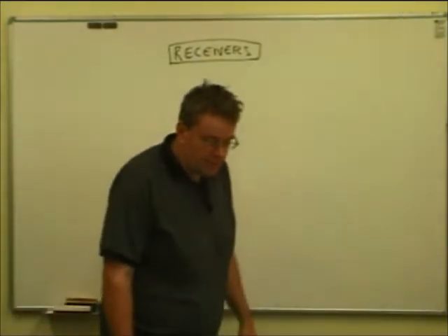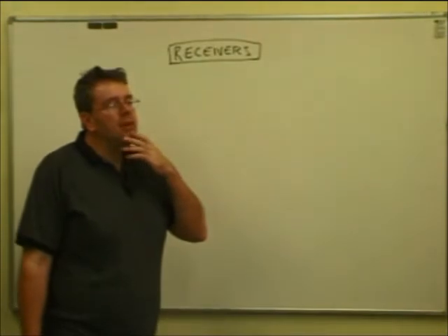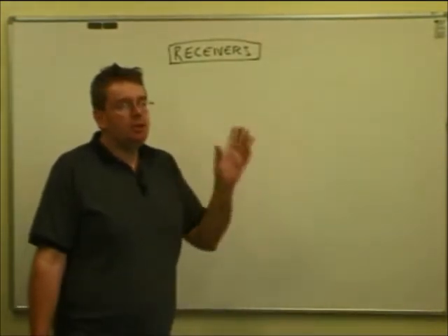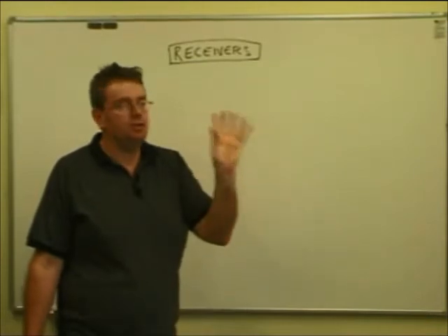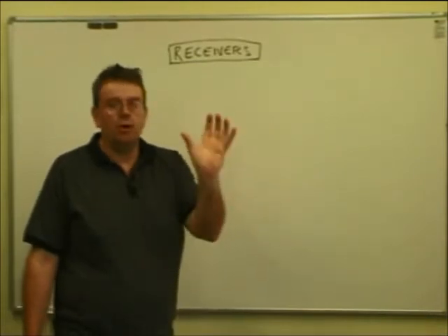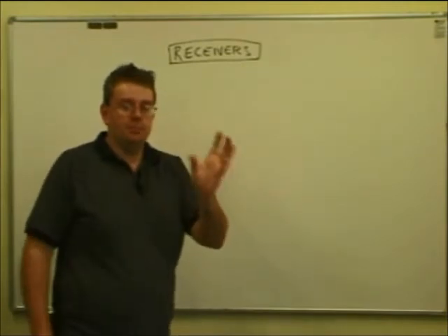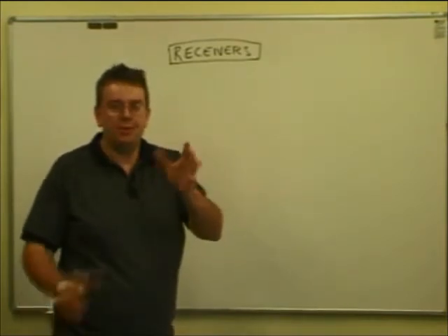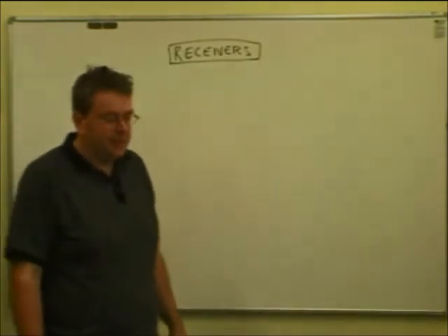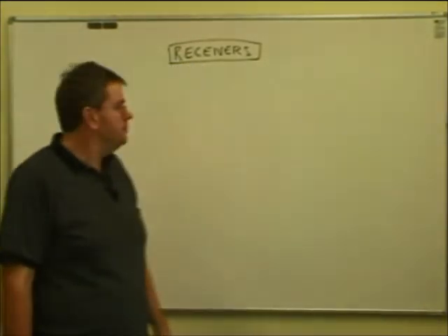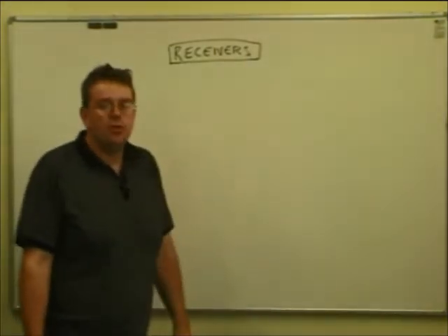That's an important receiver property we'll talk about again in a little bit, but receiver selectivity is really the ability of your receiver to tune, to listen to, if you like, the signal you want. And signals that are a bit above or a bit below in the frequency spectrum to that wanted one, we don't hear them. So we can select the one we want, but not hear other stuff, especially close in. That's called selectivity. The crystal set, just having that one simple tuned circuit, is not very selective.